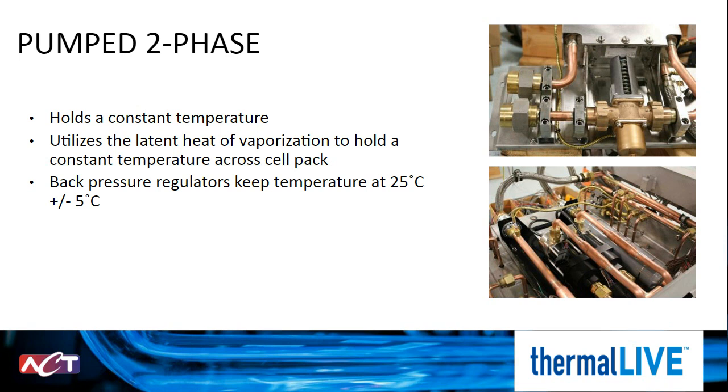Now, this technology, while meeting our design constraints and being optimal in the variable environment, is very complex. Since the condenser would be affected by the environmental temperature change, control would require intricate pressure regulators. So it is my favorite and what I believe to be the future of EVs. A complex cooling solution like this is a difficult step to take in the EV design feasibility.